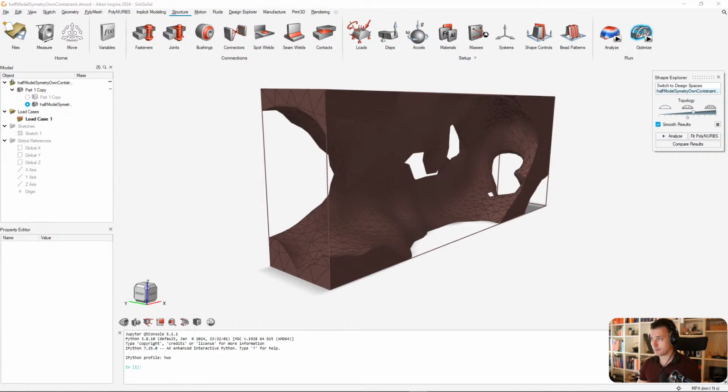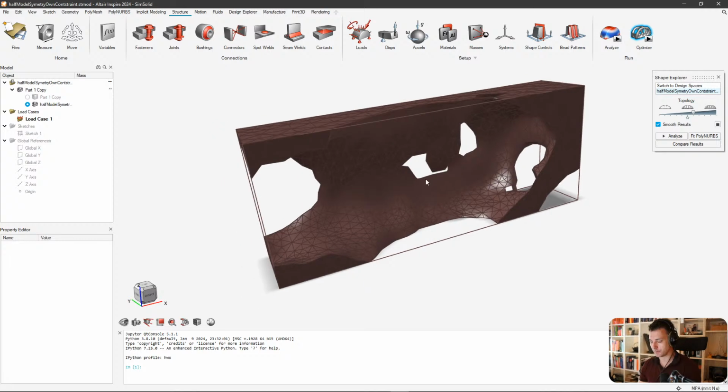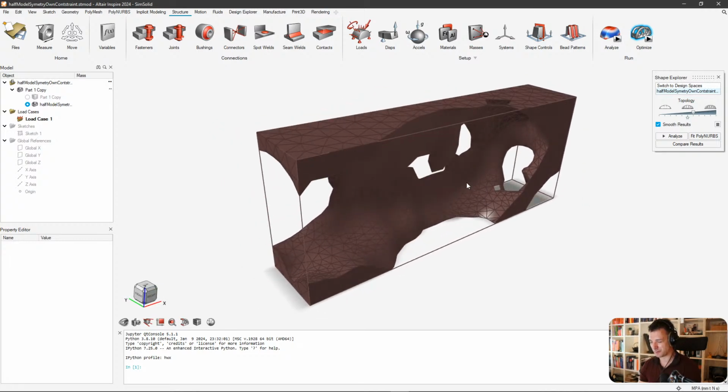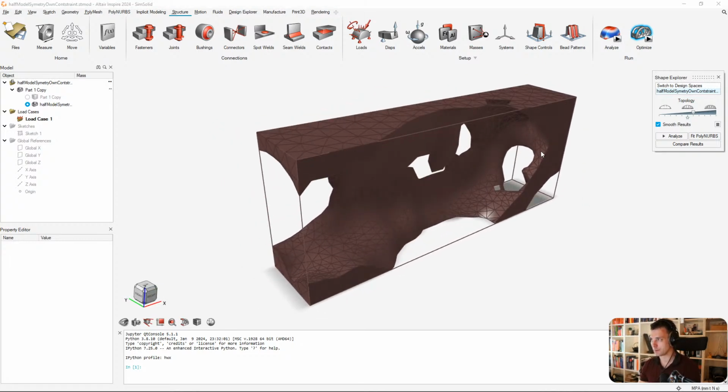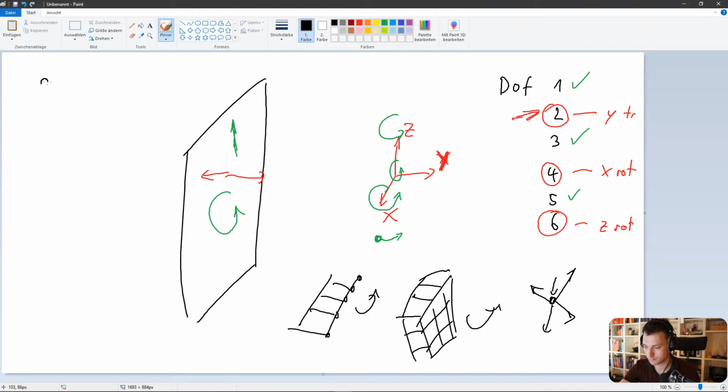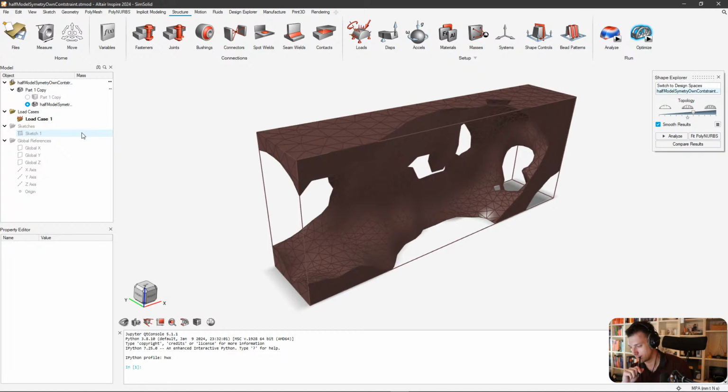Now let's get to Hypermesh, and you will notice the difference between how easy it is to do that. Let's check the dimensions again. I think that was 200 by 200 by 500. And we had an 80 millimeter minimum thickness constraint. That's pretty harsh.